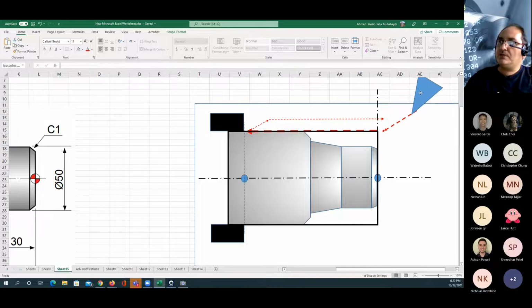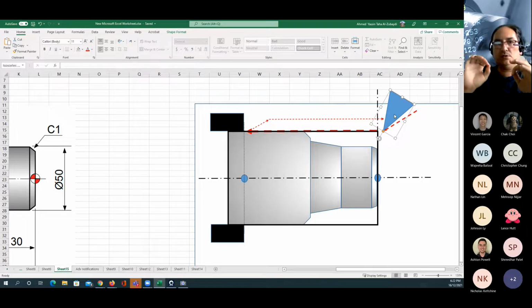So again, to go with the G00, going to that point. And this point is going to be, we said that the diameter now is 70. I'm going to send it to the X is, let's say 70. And the Z is equal to 2 millimeters positive. Then my work is going to be as following.